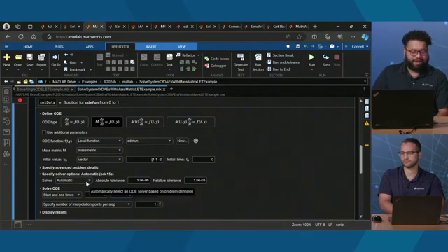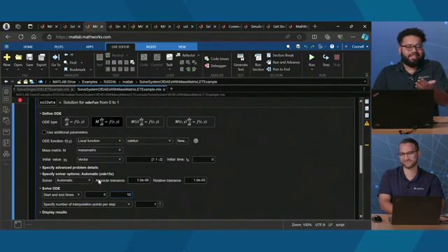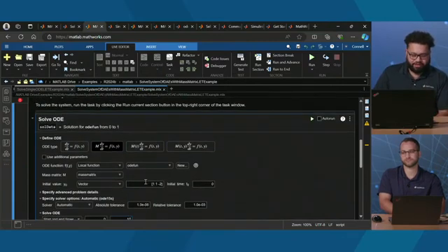There are some solver options. Again, you probably heard me say solver. If you've done a math class and you've used MATLAB, you've probably heard of ODE45. ODE45 is one of the solvers. ODE15s is another solver. You can go look up the documentation on what all that means. We could spend hours talking about it, but essentially these are numerical solvers. So Simulink or MATLAB is just going to be able to solve that differential equation for you numerically. I'm asking MATLAB to pick the solver for me. I don't really care which one it uses. I give it some tolerances to make sure the solution's converging.